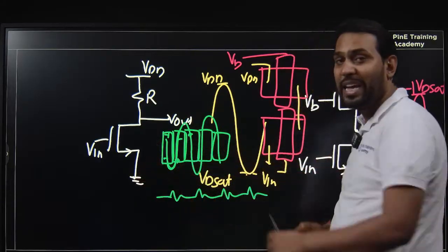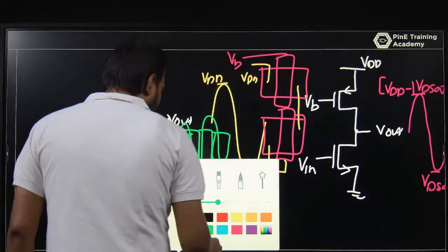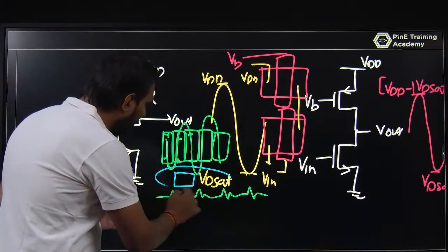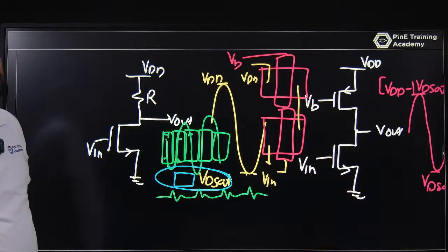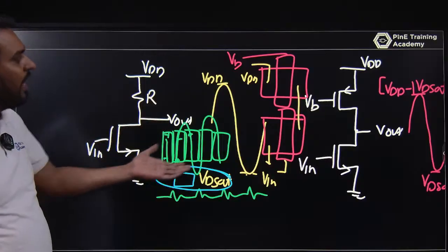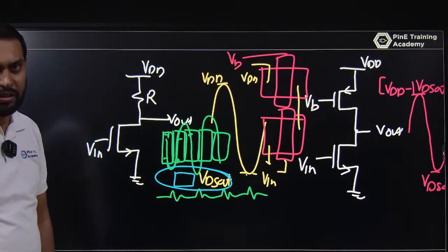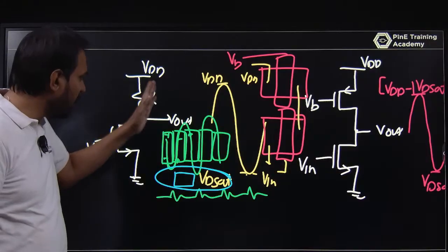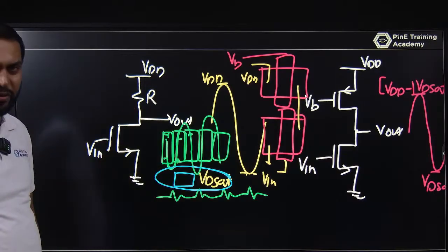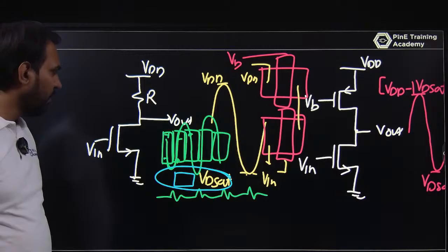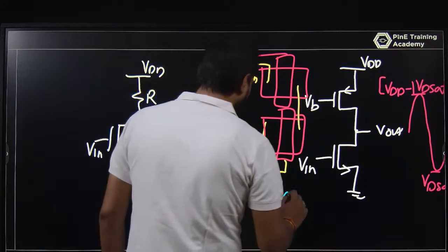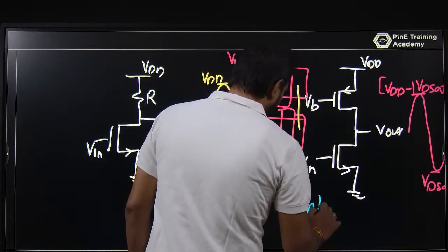You have a lot of area covered by the resistance only, and you can design a MOSFET in a much smaller area. So this is a wastage of area. That's why we are always thinking, okay, use a MOSFET in place of a resistor. So I am reducing that resistance fabrication step. So I am just avoiding that. Just like an inductor, an inductor is also very tough to fabricate. So we can replace the resistor and use a MOSFET. That's why VLSI is called monolithic, and in a single chip, you can fabricate everything.